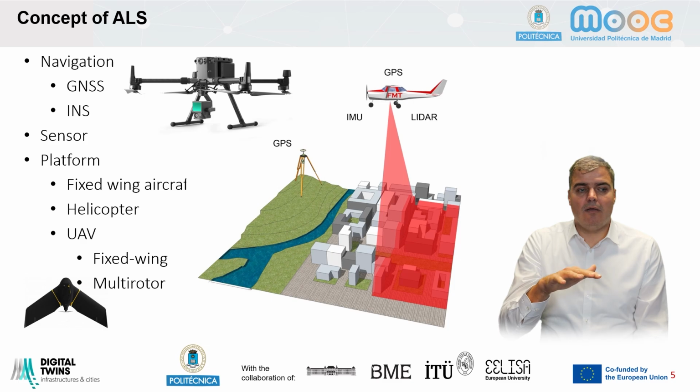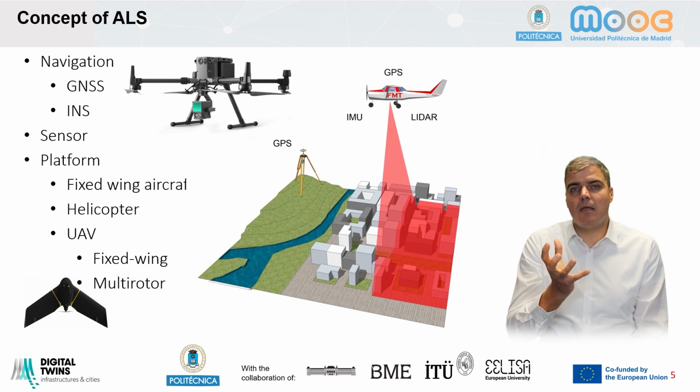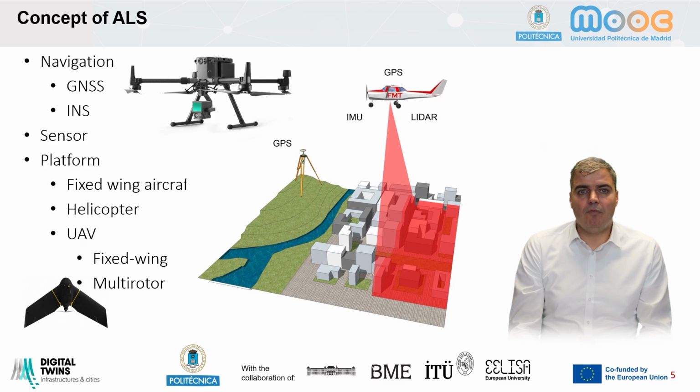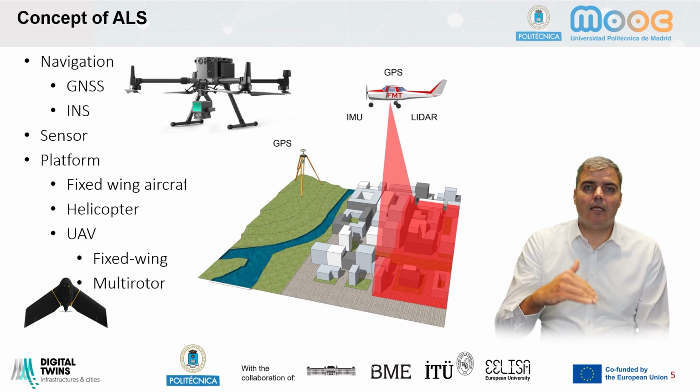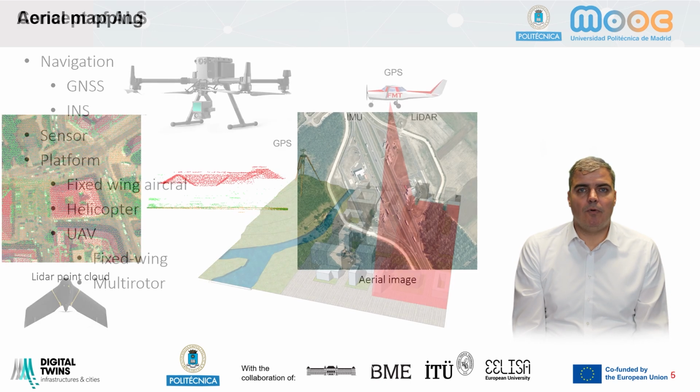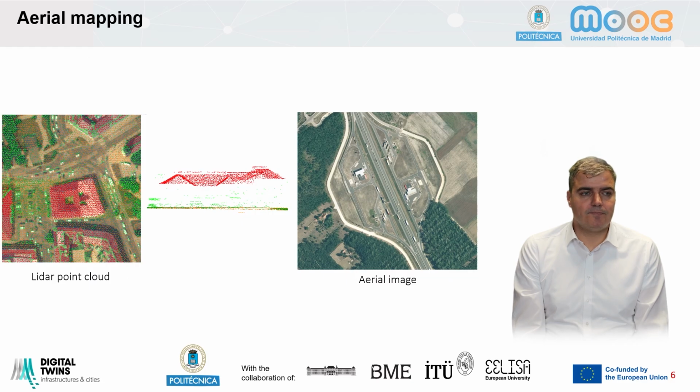And in case of a multi-rotor drone, we can use a gimbal and put different sensors on it. The multi-rotor drones are better to land and take off. They are better at following the horizontal and vertical directions, the topography, but they don't fly for long because it depends on the battery time.